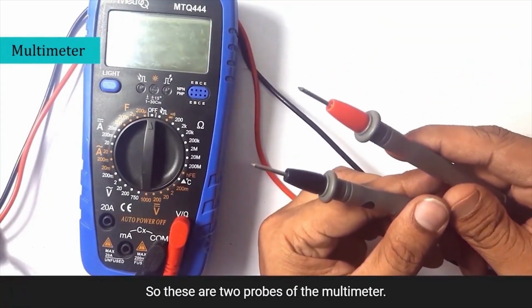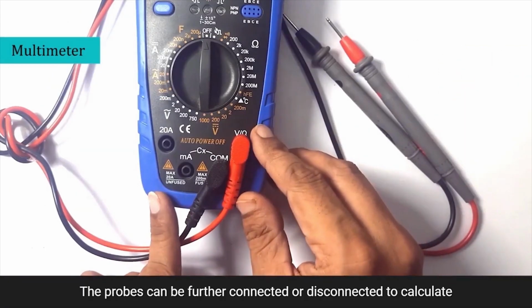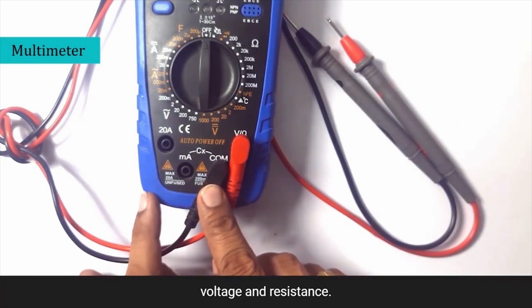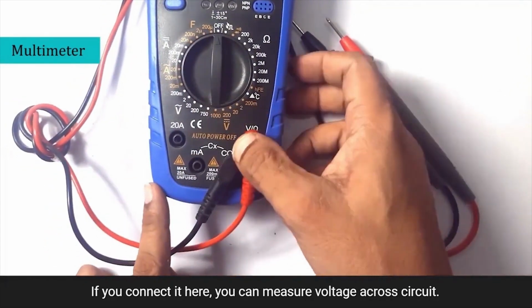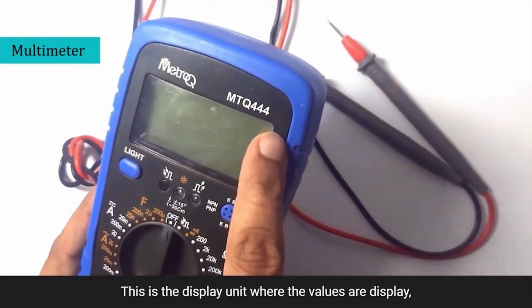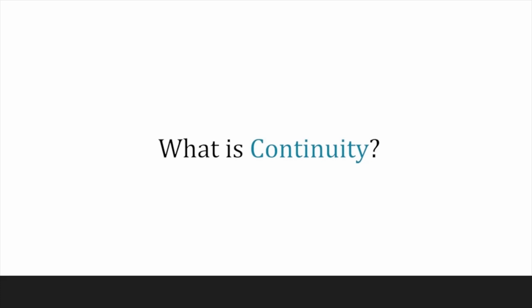So these are two probes of the multimeter. This is positive and this is negative. These probes can be further connected or disconnected to calculate voltage and resistance. If you connect it here, you can measure current. If you connect it here, you can measure voltage across the circuit. This is the display unit where the values are displayed, whether it is voltage or current.